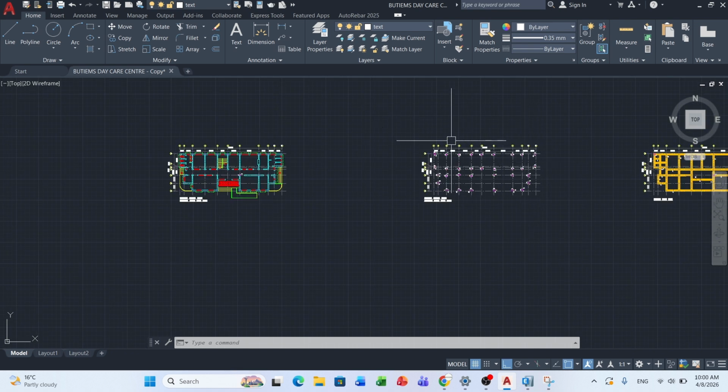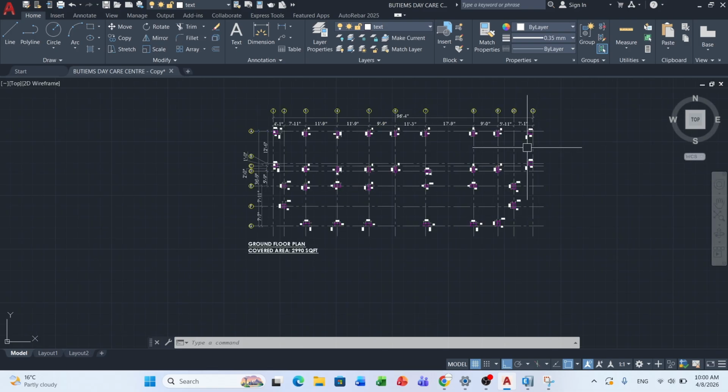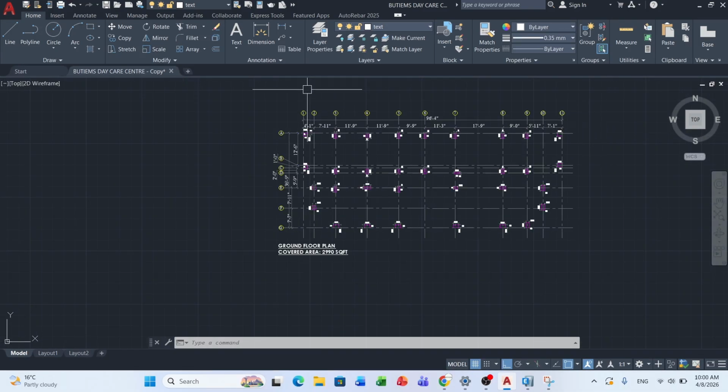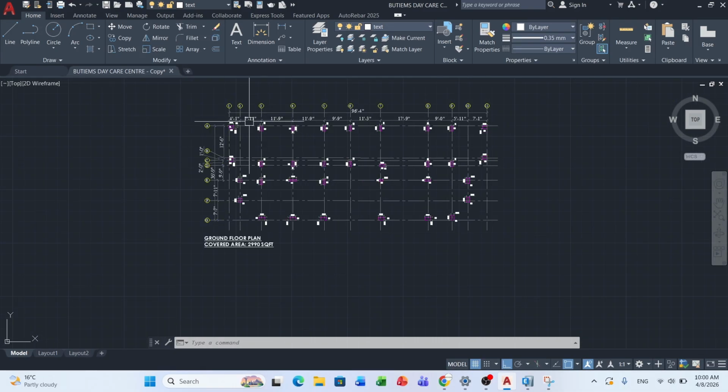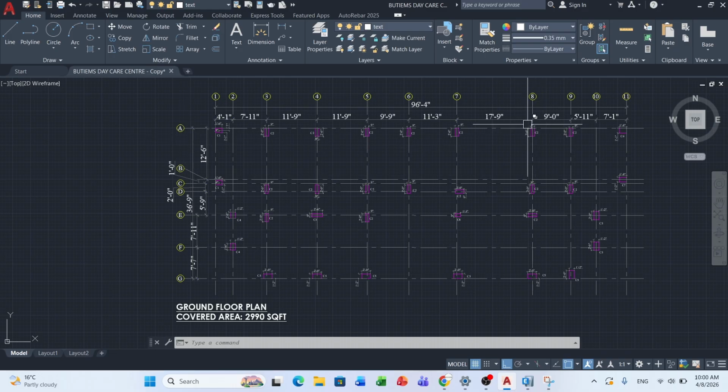First thing that we would do to this drawing is that we would locate the columns. So these are the columns that we have placed on this structure, coordinating with the architecture. So we will determine the orientation of the columns based on the longer distance of the span and as well as the loading conditions, and based on the architectural requirements as well.